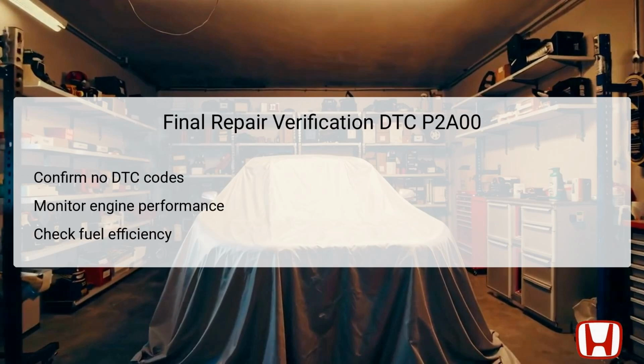Final verification is crucial after addressing DTC P2A00 to ensure that the repair was successful and the vehicle is performing optimally. Start by confirming that no diagnostic trouble codes remain stored in the PCM using the HDS. If the codes have been cleared, monitor the vehicle's overall engine performance, paying attention to acceleration, idling smoothness, and any unusual behavior.